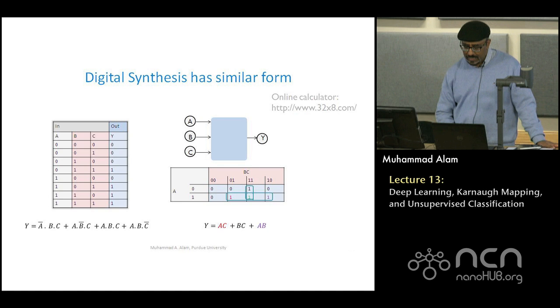This is something that you can also see in the Karnaugh map on YouTube or other places, if it's not clear, but you get the idea, you may have seen this before. And then if you want to do a Karnaugh map, how do you do that? If it's a 3-input Karnaugh map, then generally you write A on this side and B and C over there. And then you just copy this table. Everywhere Y is 0, for example, A, B and C. So this thing is 0, right?